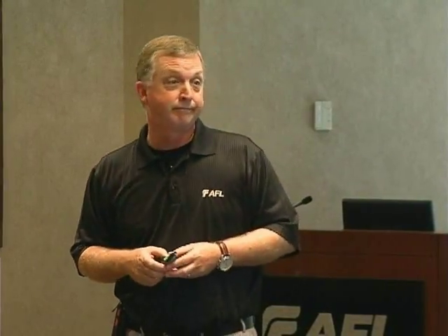There's no right answer. We want them to always buy fiber cable, right? But that's not always the answer. If I'm installing a new AMI metering system, I'm not going to go in and put fiber. We look at it from a cost perspective and logistical perspective. You can't really justify building fiber all the way to every meter just to read the meter. But if I wanted to do video, or internet, or provide triple play bundled services like some utilities do, I'm not going to do it over cellular. I'm going to have to get fiber in there. So it's just going to depend.